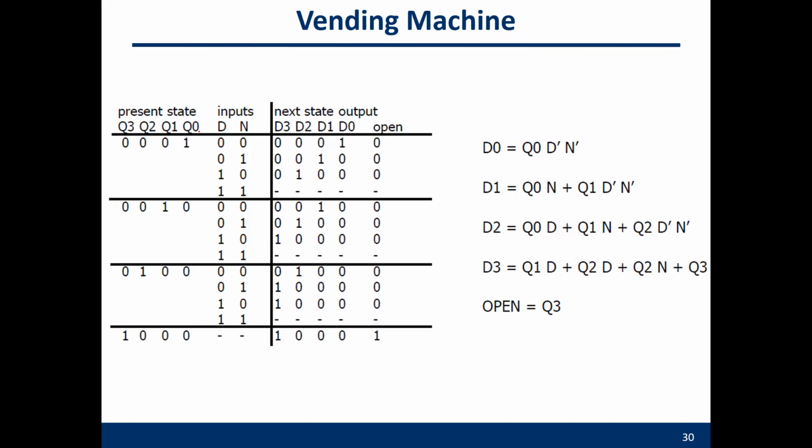Now we can also encode the state by binary like this. Because we only have 4 states, we only need 4 bits for the one-hot design. And in this case, we can rewrite the entire Boolean algebra for this machine like this. Of course, this is based on the simplification results achieved by your K-map. Any questions?